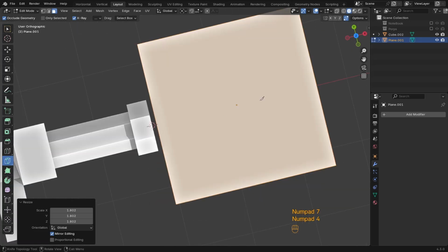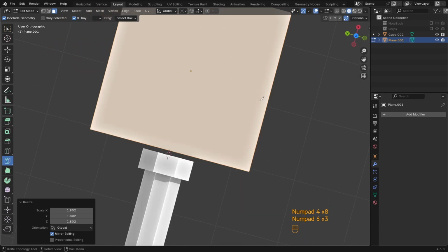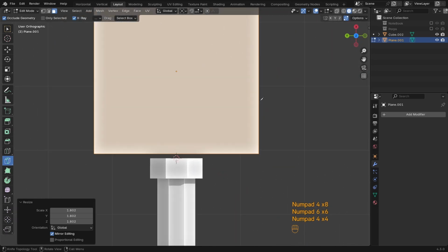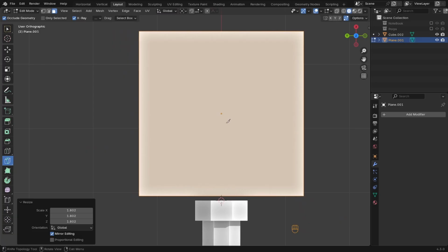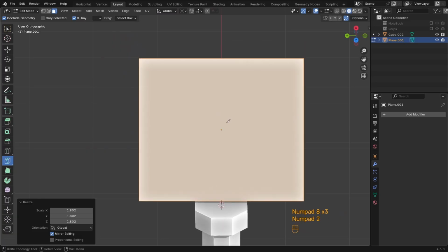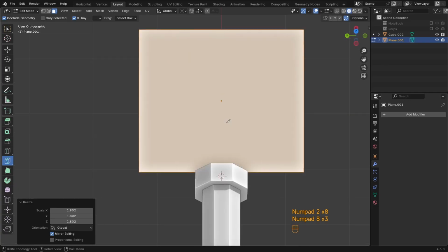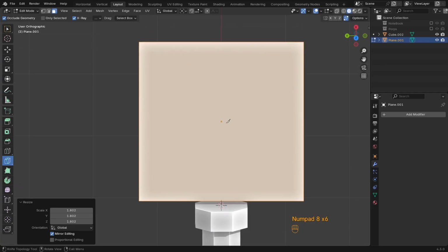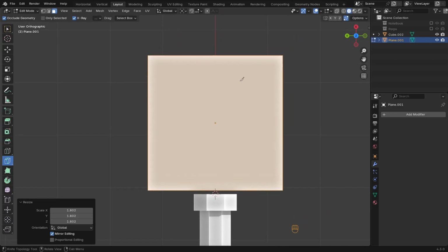Let's rotate it. You can press 4 and 6 to rotate each 90 degrees, which is very interesting and useful. And then 8 and 2 to rotate in y-axis each 15 degrees. So let's shape these. For example, we can draw a shape around this object.